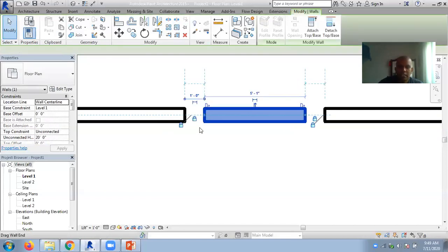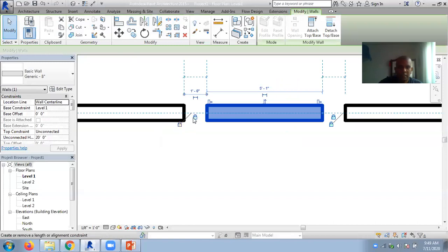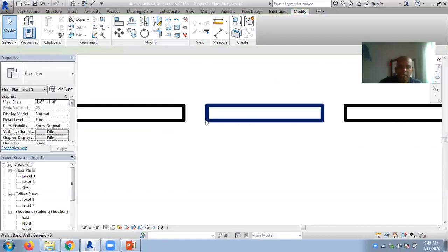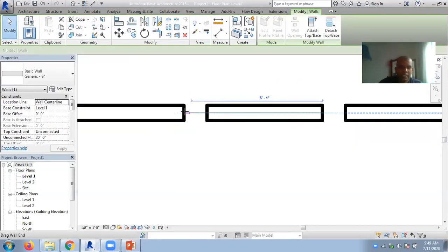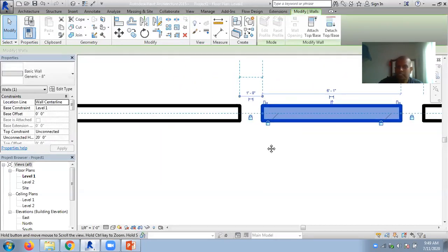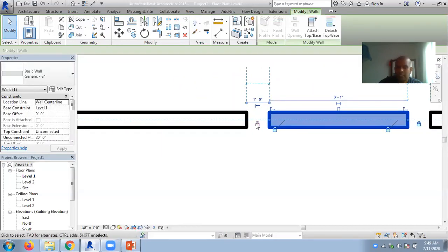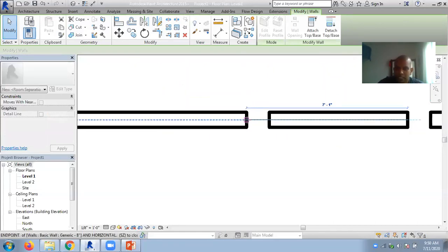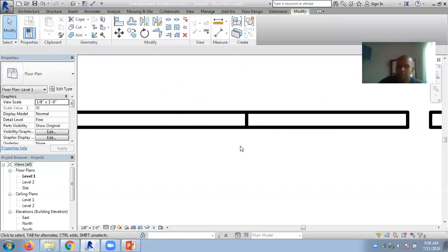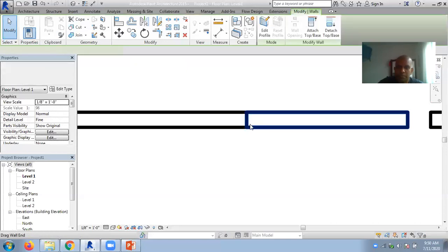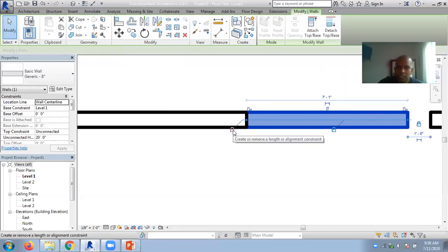When you click on this split, a lot of locks appear, meaning that you cannot just merge it by dragging and dropping, because this gap is maintained by the software, and there's a lock for the gap. If I unlock it, you can try to merge, but merging will not happen. It's just a joint now, because it's not allowed.